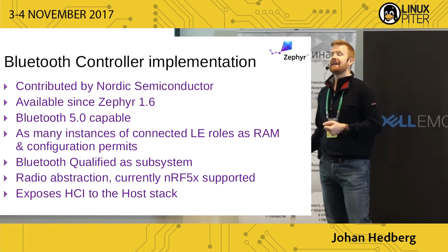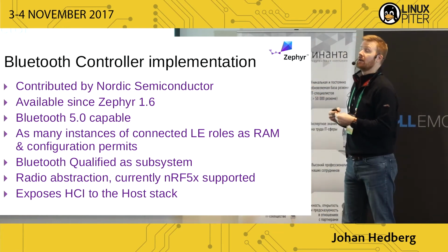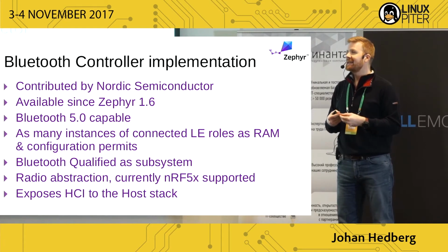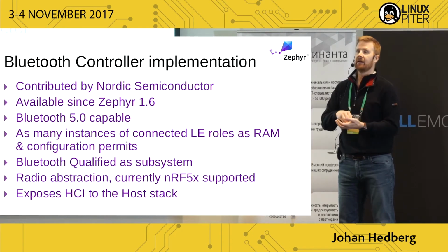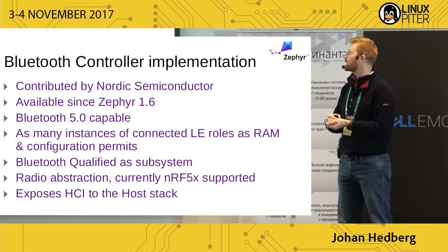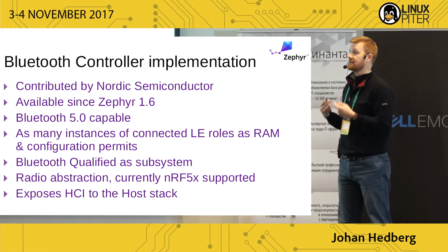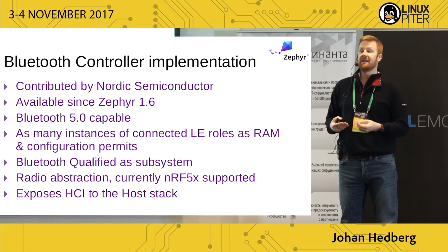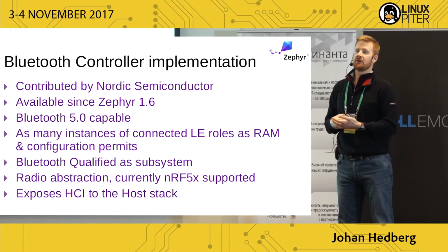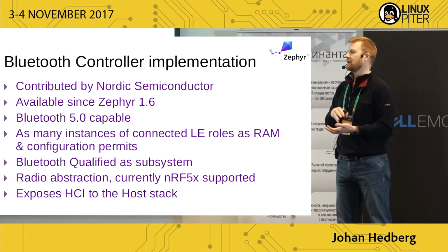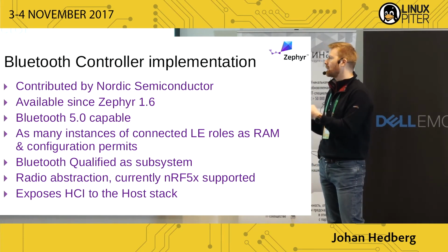In addition to being the very latest Bluetooth specification, it's actually very flexible. A common limitation of Bluetooth controllers is that when they are in slave role, they can only support a single connection. With the controller support that we got from Nordic, you can do as many connections as the available runtime memory allows for tracking the different connection contexts. Another limiting factor, of course, is the airtime: what kind of connection parameters you have, how much time the different connections require for themselves.